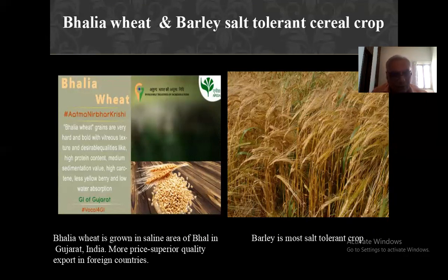And in India, Karnal, previously the soil of Karnal was a better soil. But what happened? They used excessive irrigation water. In the Ganga and Brahmaputra river areas, they use plenty of water for rice and wheat, and they have deteriorated the soil, and now the soil has become saline and alkali soil. So they are growing barley, wheat, and also rice. The rice crop can be grown in saline soil because it requires standing water. When you fill the soil with standing water, the salt present in the soil is diluted and the rice crop is grown successfully in that area, particularly in saline or alkaline soil.